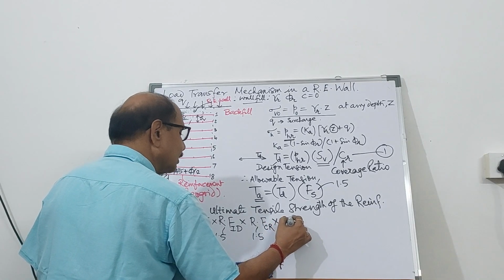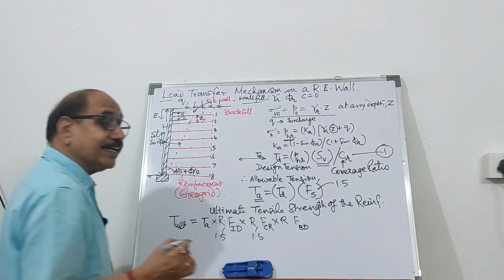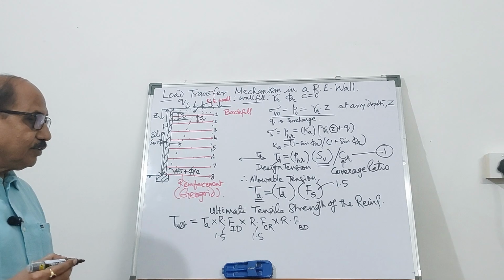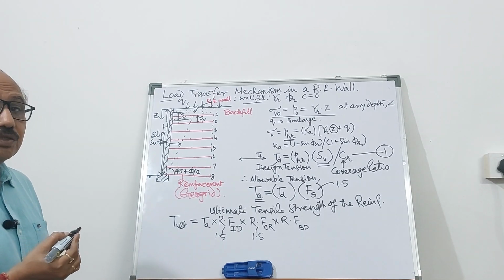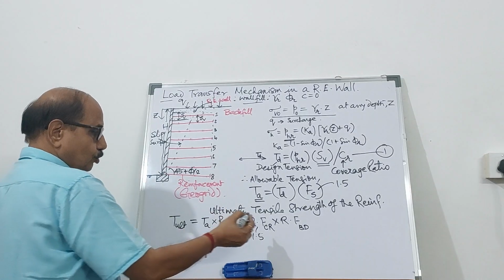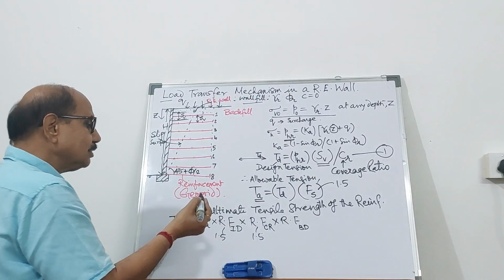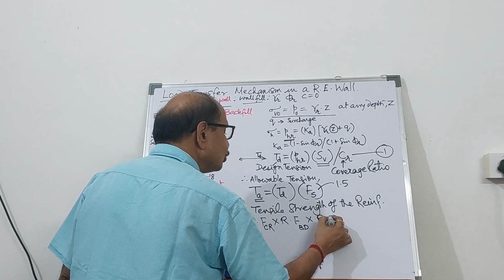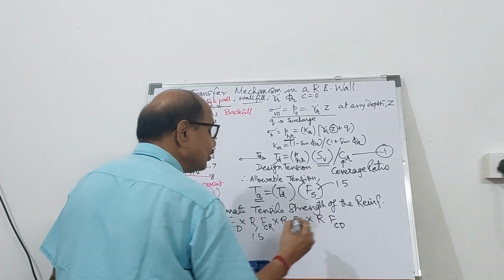Then the reduction factor due to biological degradation. If your reinforcing element is biodegradable, you should take the appropriate factor; geosynthetic is non-biodegradable. And the reduction factor for chemical degradation.